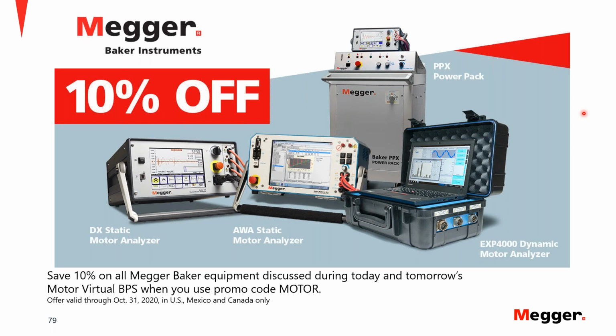Okay, first, yes, it is possible to do surge and check for partial discharge. Partial discharge occurs when you have changing conditions of the voltage. You don't typically see partial discharge when you have DC. You see partial discharge when you have a voltage that's rising or dropping, and you see the partial discharge start or finish.